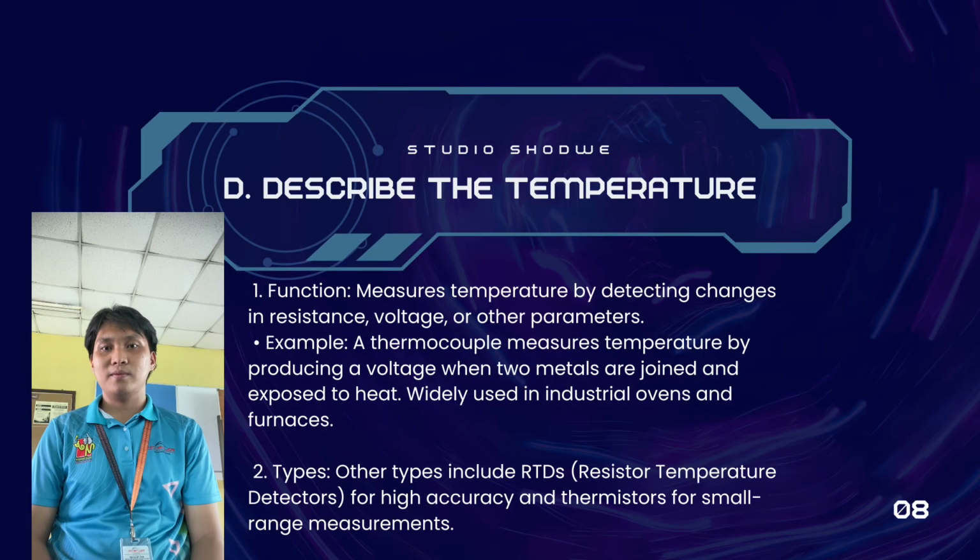For my slide, temperature sensor. Function measure temperature by detecting change in resistance, voltage, or other parameter. Example, a thermocouple measure temperature by producing a voltage when two metals are joined and exposed to heat, widely used in industrial ovens and furnaces.